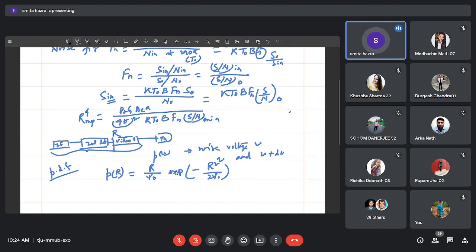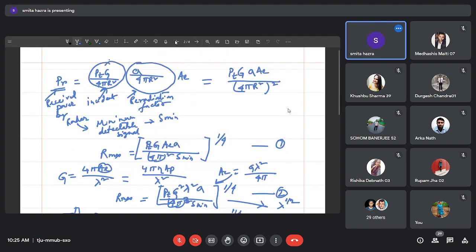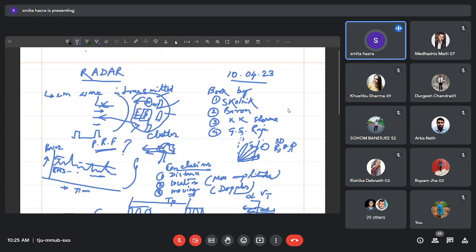Now we are led to the false alarm probability, when the R value exceeds the VT level. If we integrate, because this function is a probability density function, to get the probability we have to integrate it over the total range. What is the total range? Vt is less than R, less than infinity, isn't it? Because if we go back to that curve, if R exceeds Vt, the lower level is Vt and the upper limit may go up to infinite value.